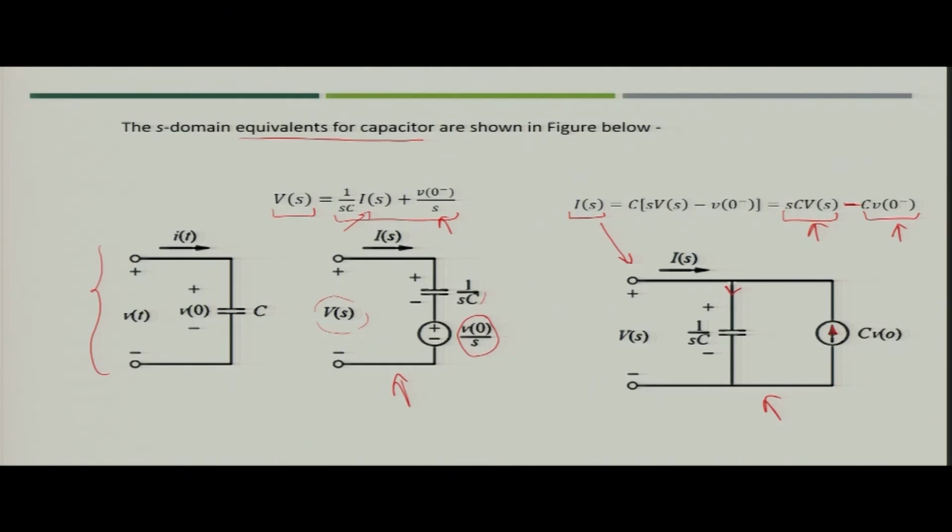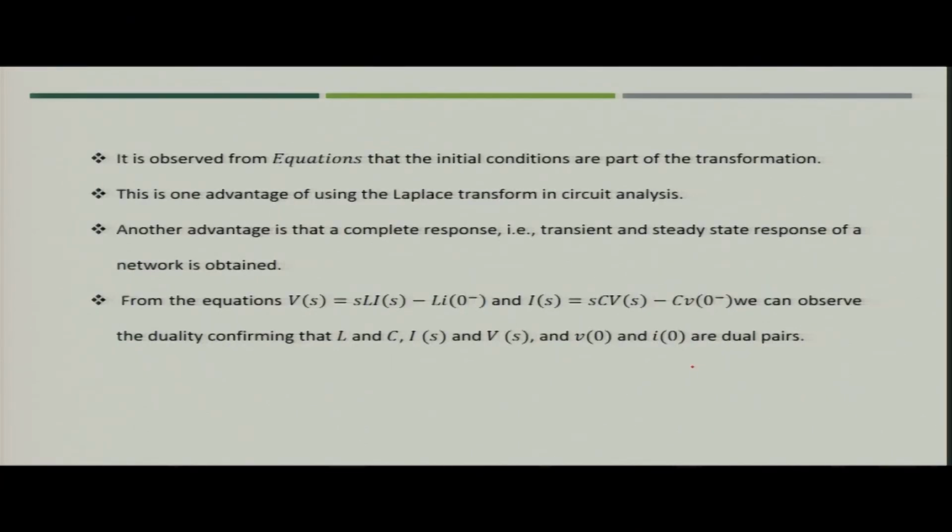So, these voltage and current equations can be used whenever required, to solve the circuit according to your convenience. From these equations we observe that the initial conditions are now part of the transformation, so we need not worry about how to incorporate the initial conditions in S domain, because the S domain equations take care of them.